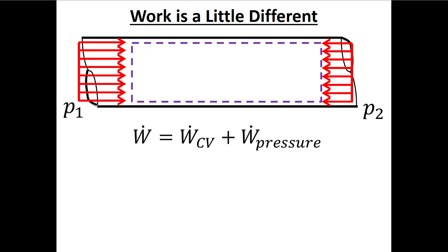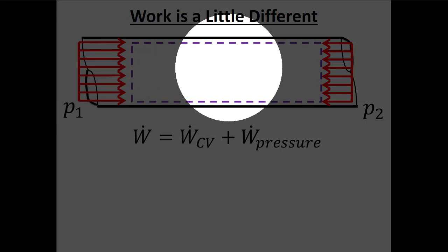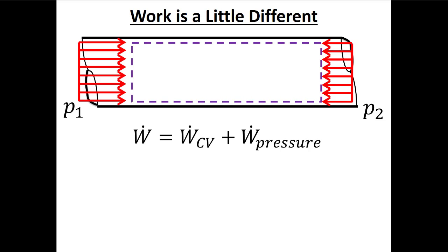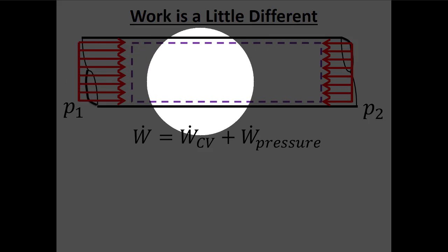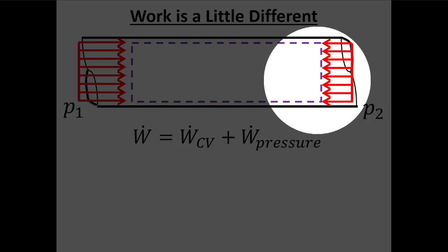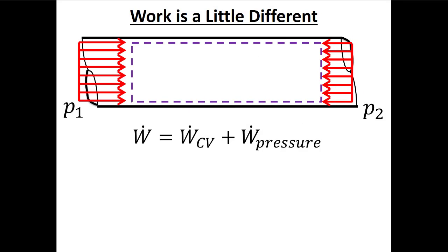So we don't lose energy in terms of kinetic energy because conservation of mass requires, in this case, that the velocity stays the same. But we lose some potential energy in the flow. So what happens is as we move along this pipe, the pressure drops. So we have a pressure drop in the pipe, right? So we pay for the motion in the fluid by this potential energy. So we have less potential energy stored in the fluid because the pressure is dropping, right?